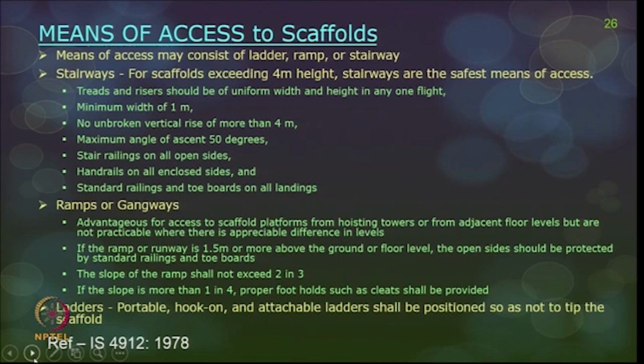There are so many ways of means to access. You can have portable ladders, hook on ladders and attachable ladders. Hook on ladders and attachable ladders are generally designed along with the scaffolds, so along with the scaffold it comes with the proper design, and portable ladders are designed separately. We will talk about the safety of portable ladders in the next few slides.